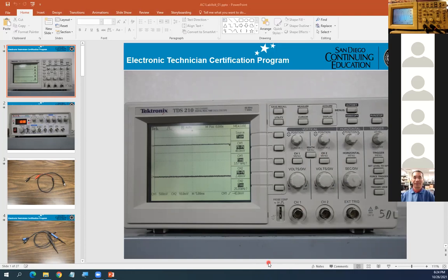Automatically it triggers and displays what you want. You can see the sine wave on the screen. But the important thing here, when you press the auto set measure, do not touch channel 1 or channel 2 or tab. Don't change anything. Auto set measure means the scope does it. It ignores whatever you try to set by hand. That is the key point.